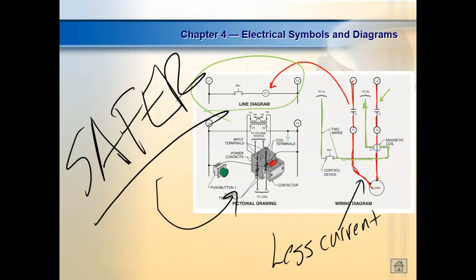Got one advantage. It's easier to run because it's flexible. Stranded wire is flexible. It's real easy to run. It's real easy to pull. Right? You understand that. But it's harder to terminate. The advantage of solid wire is that you can terminate it or splice it.